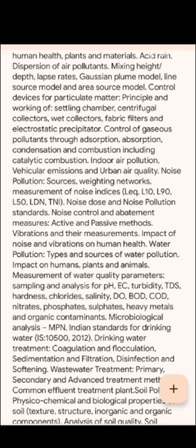Water pollution. Types and sources of water pollution. Impact on humans, plants and animals. Measurement of water quality parameters. Sampling and analysis for pH, acidity, turbidity, TDS, hardness, chlorides, salinity. DO, BOD, COD, nitrates, phosphates, sulfates, heavy metals and organic contaminants.